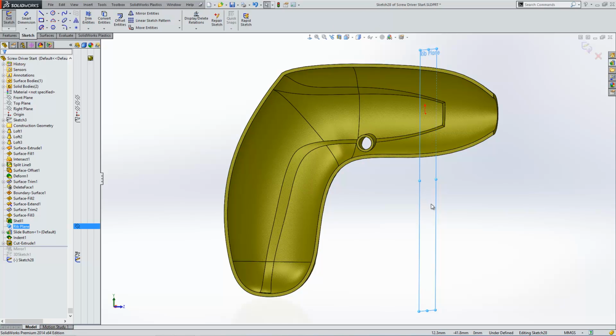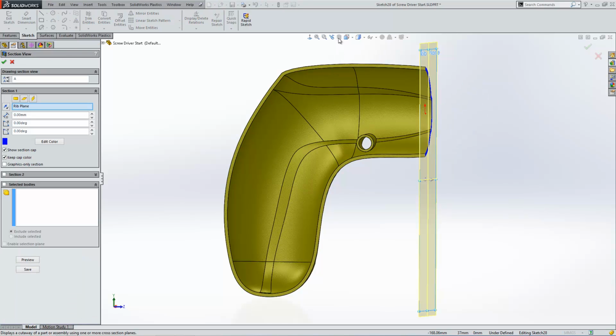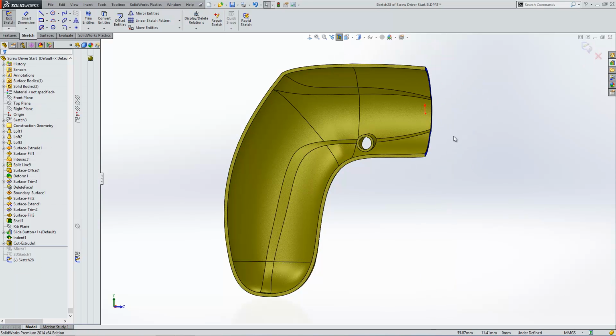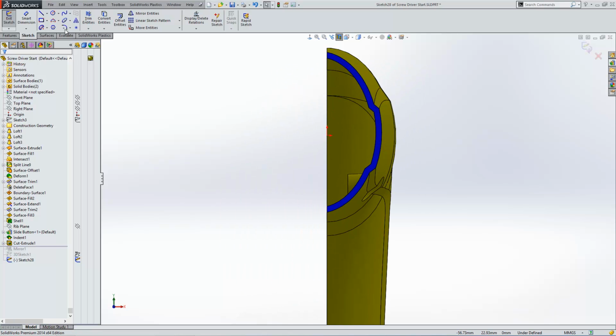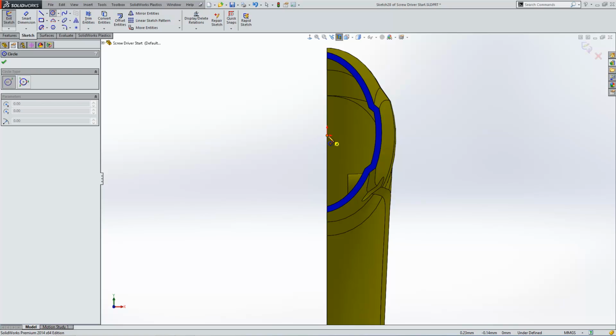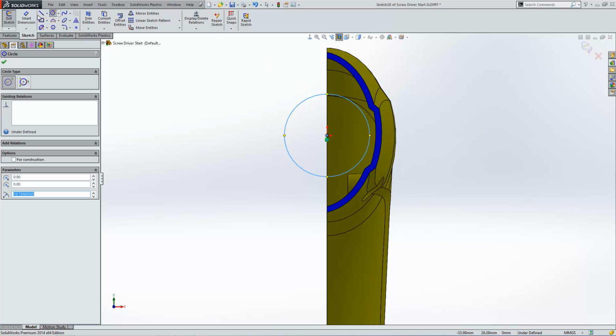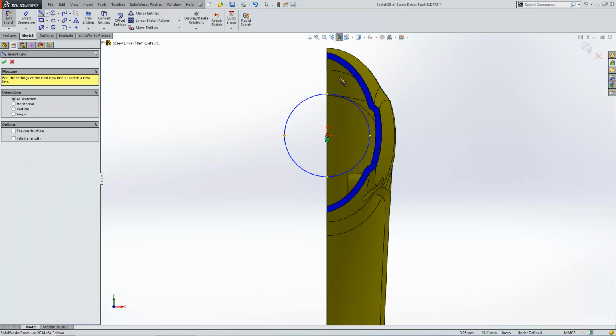And when you're drawing a design like this, the best way to approach it is by using the section view tool. If we section into this design, we can then see straight through it, which allows us to draw the rib a lot easier. The shape of this item would just simply be a circular cut out into the design with just a straight line going across the middle.